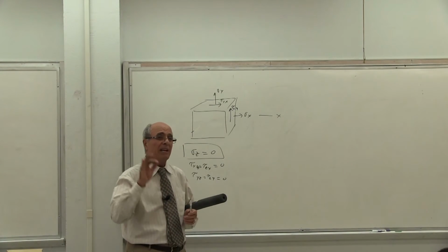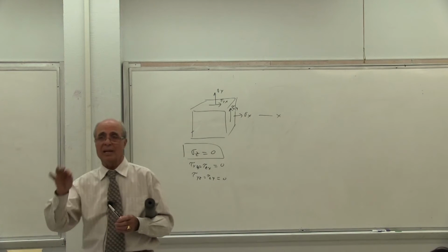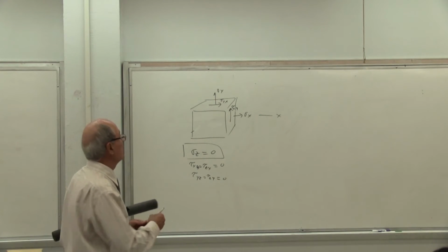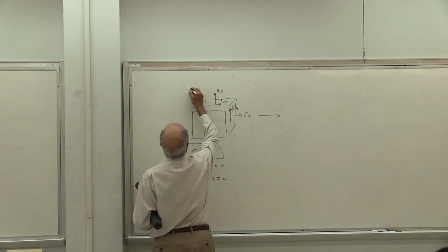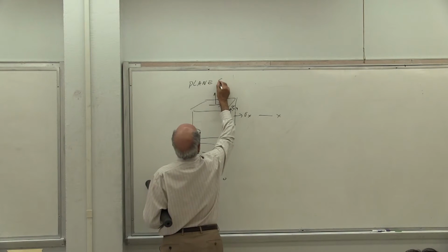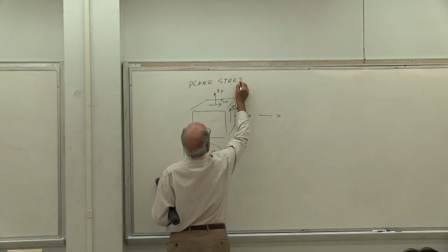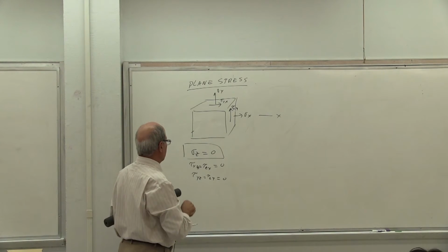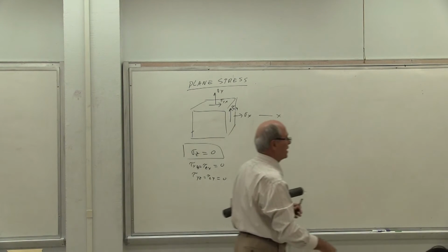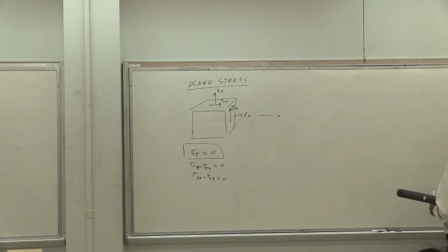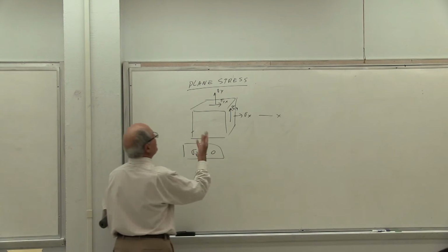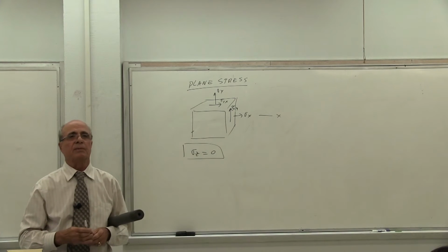So for example, R always was sigma x minus sigma y divided by 2, here it becomes epsilon x minus epsilon y divided by 2. Then always plus tau xy to the power of 2. Now tau becomes gamma, not even gamma, gamma over 2. That's right. So it becomes gamma xy over 2. Notice, just add a 2 in every equation, it is exactly the same. So every process is the same, every result the same, except the minor difference that I'm going to explain.